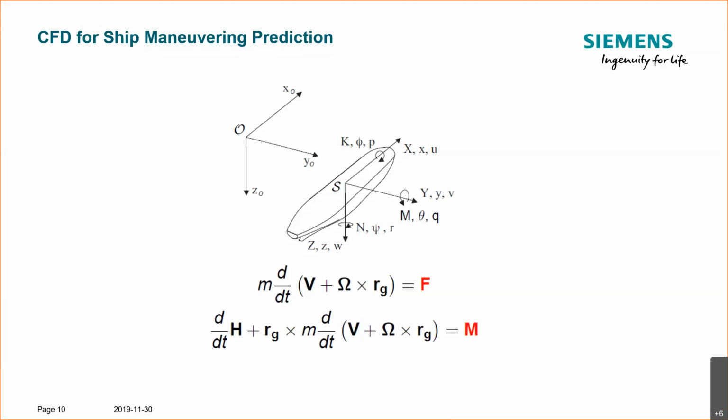And we directly see here, indicated by the red color, where the trouble arises for the hydrodynamicists. So what is not known is how to express the external forces and moments. Apparently in maneuvering, we have to deal with and address an array of force contributions. So there will be force contributions from the hull itself, the resistance to forward motion, to sway and yaw motion.